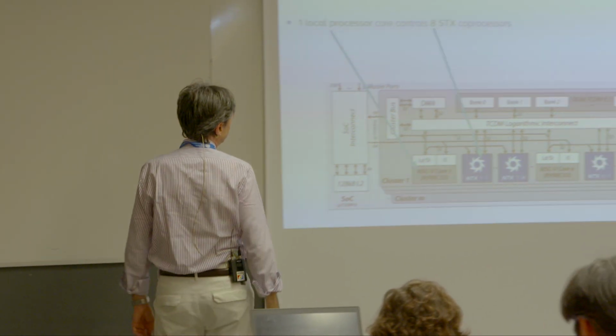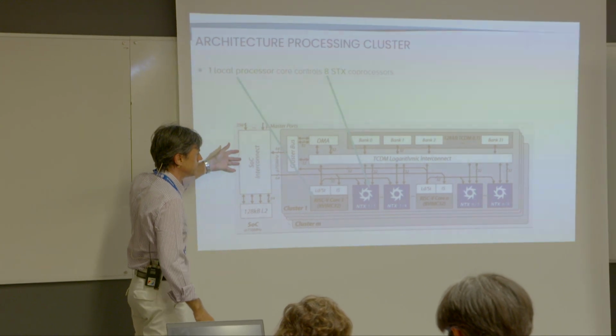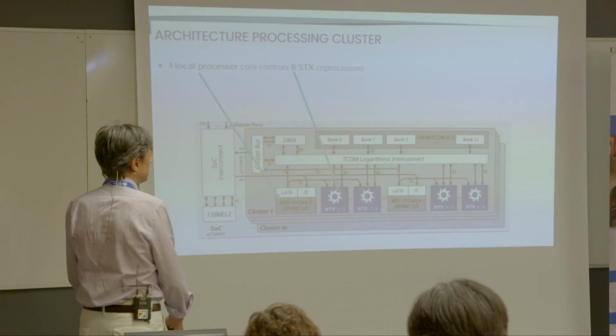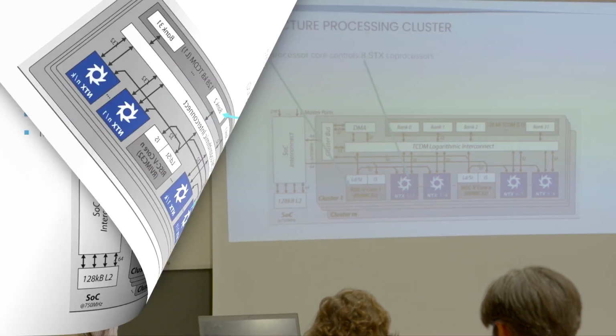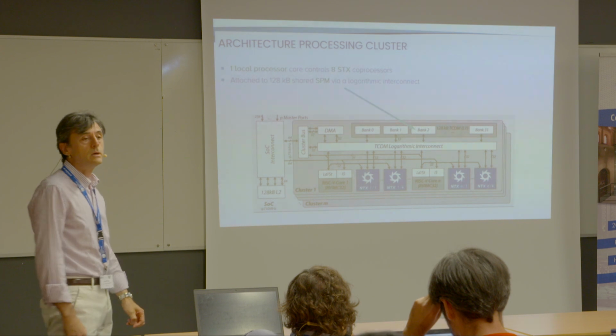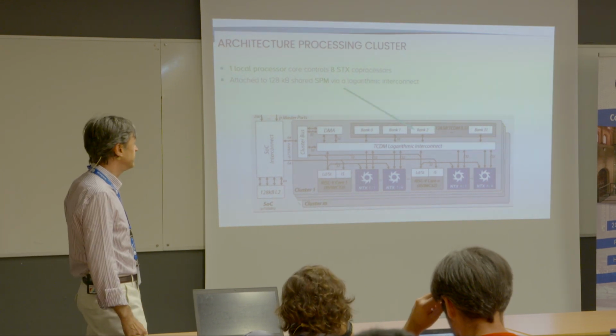On this side here, you have the interconnect to the NOC that we looked at the very beginning of this story. This is the internal memory, called here TCDM, tightly coupled distributed memory. Anyway, it is a kind of scratchpad memory that is put there to exploit locality.